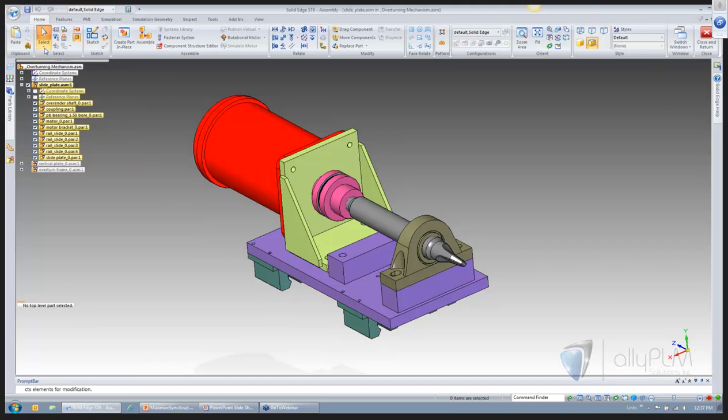I'd also encourage you to hover over the Select tool and read the quick tips. It tells you that Control Spacebar and Shift Spacebar are some common workflows to change our selector. You'll note that right now the icon of my selector is in part priority mode. The glyph next to my arrow has a little icon that is very much the same as the icon in our Pathfinder. It emulates a part.